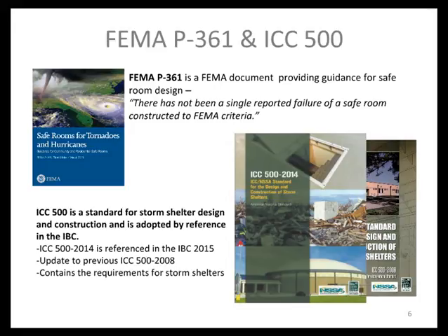There was a 2008 edition of this, which is talked about in previous IBC editions, but it wasn't mandatory. It said something along the lines of, if you're going to do sheltering, then you should, and I'm paraphrasing, use the ICC 500 document. In 2015, it says you will do sheltering in these conditions, which we'll talk about today, and you will use the ICC 500 2014.